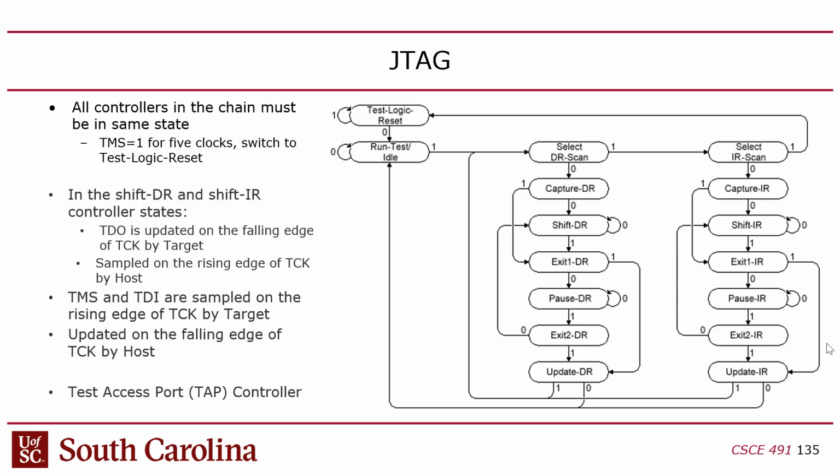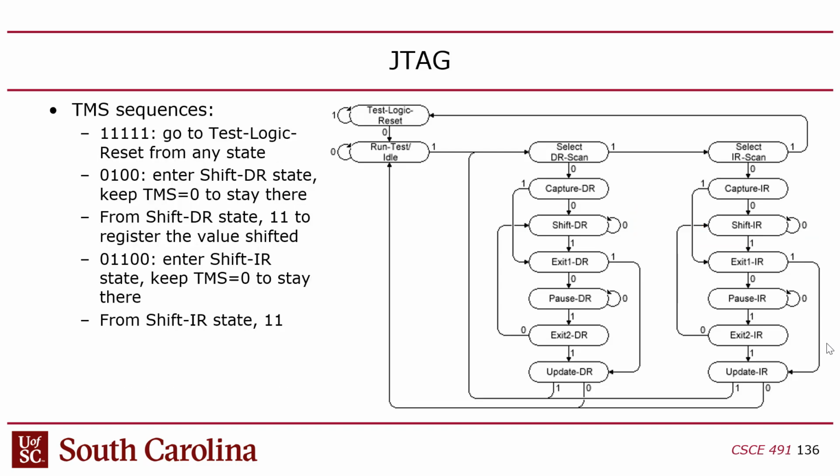So you can plug a bunch of things in the JTAG chain, and you do a JTAG scan using this approach, and it'll identify them. There's a unique identifier, and then of course you have to have a table of identifier IDs to device numbers, right? It's like a MAC address. Every ID is this device, right? So every FPGA has its own unique JTAG ID, which is stored in a table, right? Make sense? So it's very similar to daisy chain SPI, except it has this cool test mode select feature. Okay.